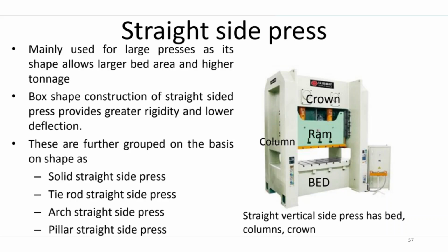When you are measuring only toughness from your stress strain curve, the area under the curve, that will be static. In tensile testing, you're stretching your material at a very slow rate, right? So that's why it is one of the static types of testing, not dynamic. In case of Charpy, the hammer comes on the specimen at very high velocity. That's why it is called impact strength, impact toughness.